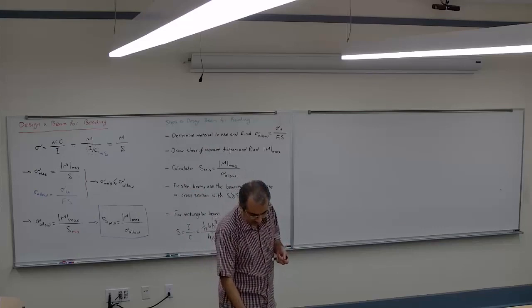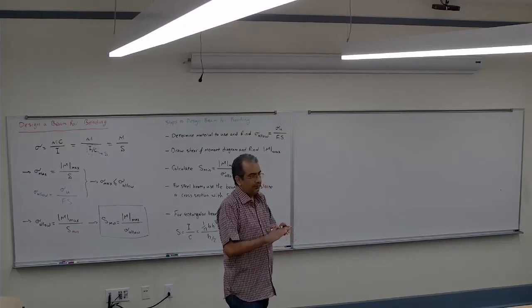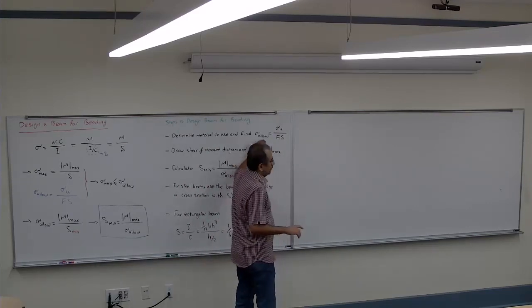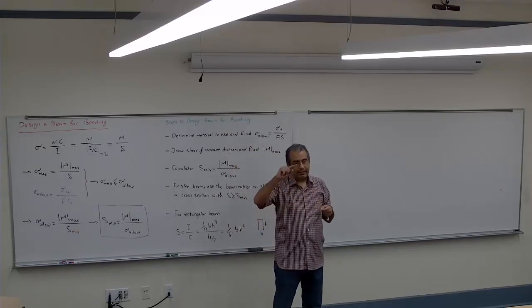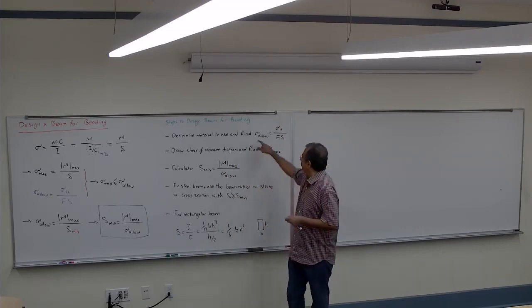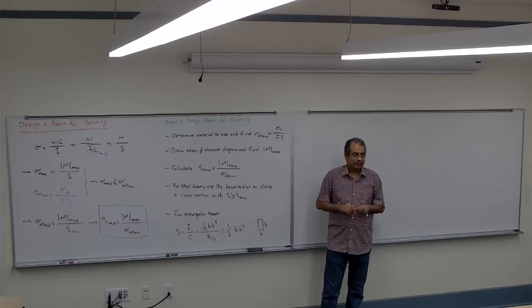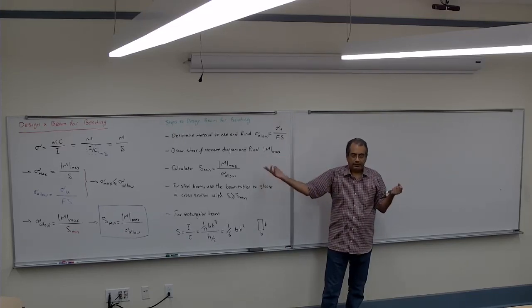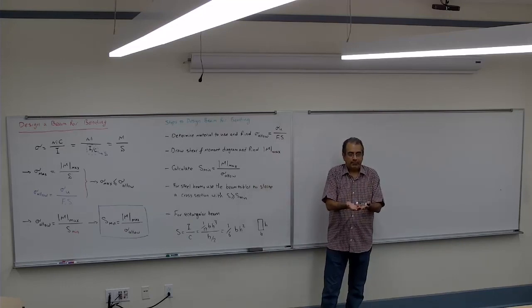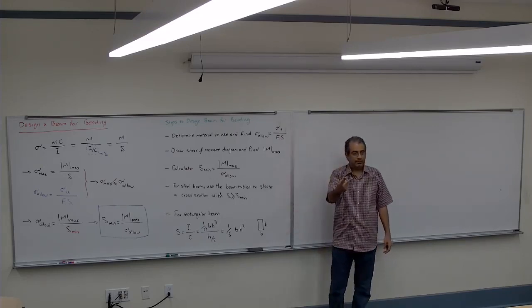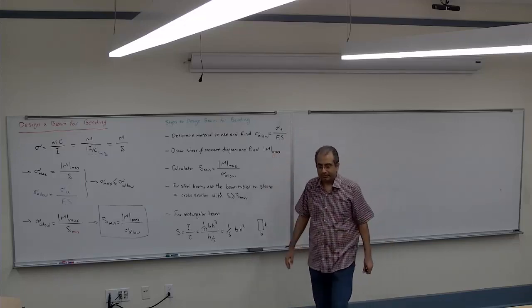Everything that we deal with here is going to be the same. Then, if you have a material that behaves differently under compression and tension, once you have to find the maximum M for the compression, once you have to find the maximum for the tension. So remember that. Here we are not dealing with that, but in the real world, for example, concrete is one of the examples. Concrete behaves differently in compression and tension, so you are doing this 2 times. Once for the compression, once for the tension.